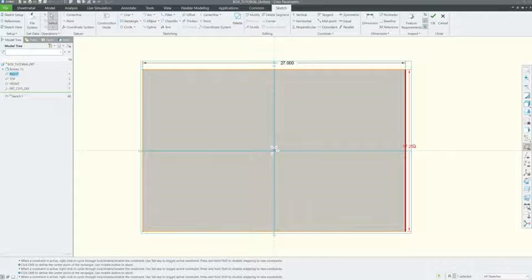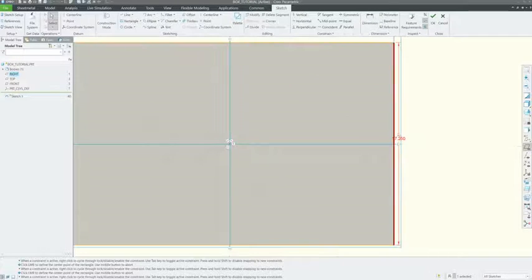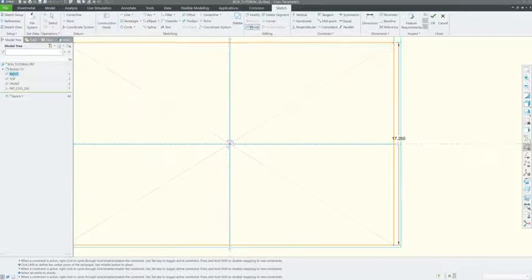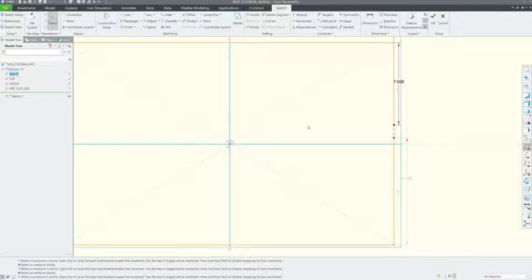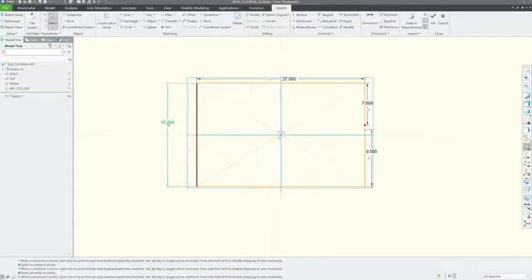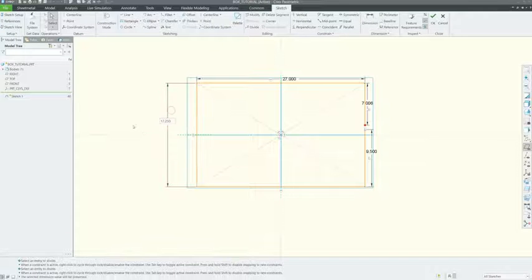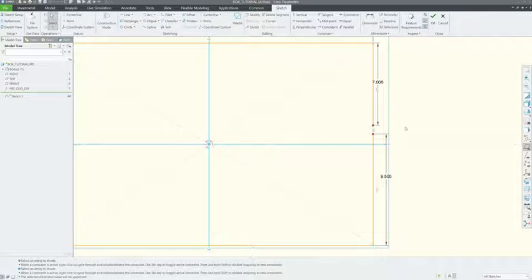Okay, here we want to divide this side, so we click Divide, click in 2 points, and I click here and delete this middle segment. Then dimension it to 9.5, and I want this gap, this dimension should be locked. Once it turns black, it's locked. It's not modifiable unless you type it in.